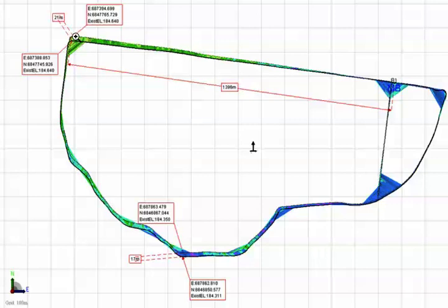there is a significant difference at the furthest point away from the master benchmark, which is about 1400 meters, 21 meters difference in the horizontal. So those lines should overlap perfectly if the coordinate systems matched perfectly.